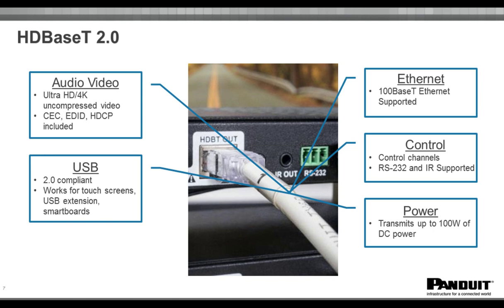There's also different HDBaseT chipsets out there. They're all manufactured by Valens out of Israel, and they have different specifications. So now there's new HDBaseT chips where you can run them over fiber. You're not going to get that power capability, but you're going to be able to go a long distance. There's limited distance HDBaseT chips for those budget-friendly solutions, and there's extended distance HDBaseT chips. They can actually run up to 150 meters over a single Cat5e cable now.